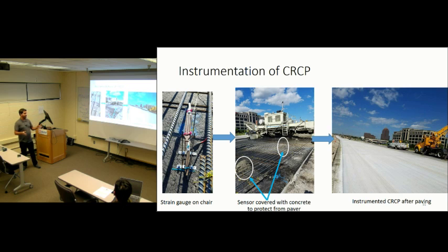And the paver, with the same concrete, would come back to that location in about 10, 15 minutes. So it doesn't affect it drastically. It starts setting slightly ahead of or later than the concrete on the other side, but it doesn't affect it too much because concrete takes 5-6 hours to set, and we are just putting concrete to protect the sensor 10 or 15 minutes earlier, same sample from the same batch.